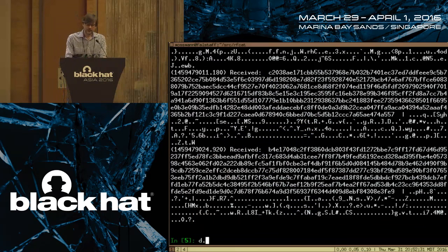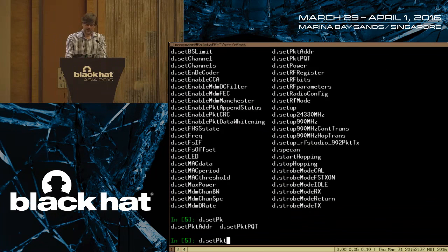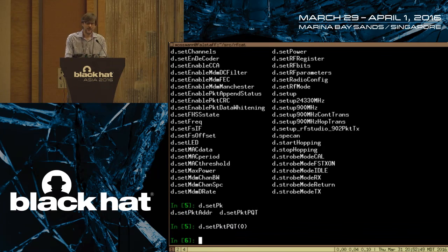So what I need to do is tell it to turn the preamble off. And the command here is packet preamble quality threshold. I'm going to set the preamble quality threshold to 0, which says ignore the preamble. Don't expect 1, 0, 1, 0, 1, 0, 1, 0, 1, 0 at the beginning of the packet. And the other thing I need to tell the Yardstick 1 is what to look for to detect the beginning of the packet.